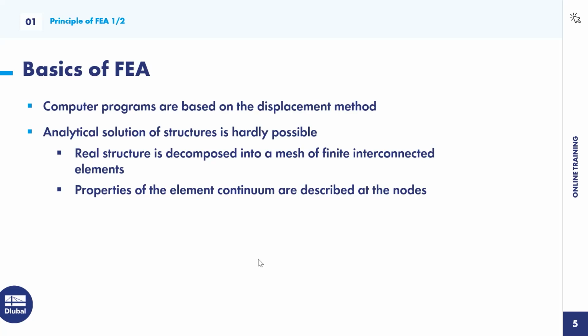We will have, on the one hand, connections between two finite elements, and within these connections we have linked degrees of freedom. You can imagine a plate connected to another plate, and at their intersection, let's say, the deformation in the z direction, so in the vertical direction, must be the same.